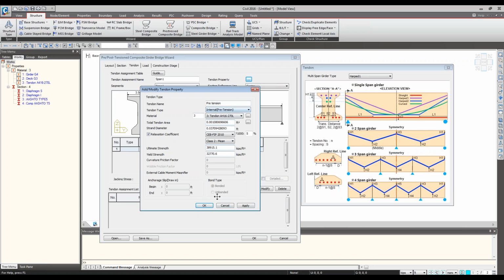For the post-tension type, you can actually define the bonded or unbonded type. Some of the questions that I received in the past are such as, according to your agency regulation, you have to disregard the unbonded tendons. That way, you can simply define it unbonded and consider the different properties that come with the unbonded types. Or if you completely have to neglect them, you can simply just not define them at all. You have all the flexibility.